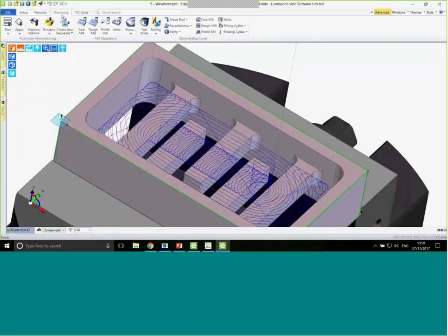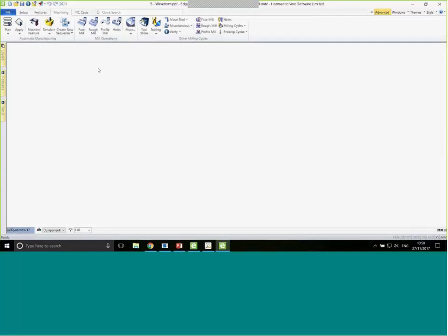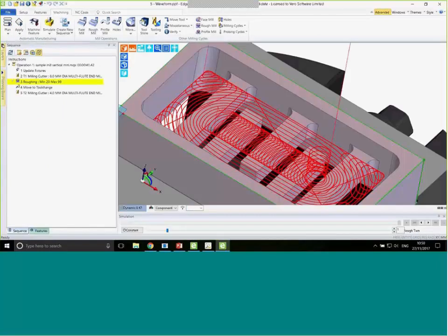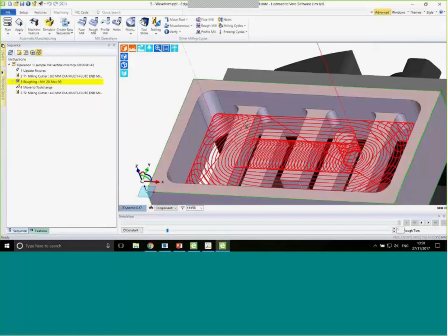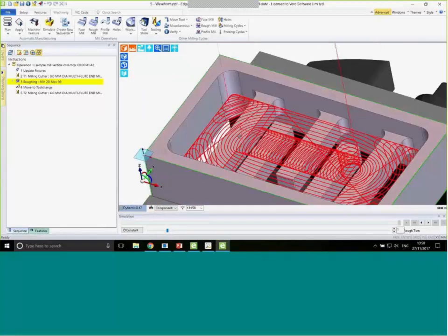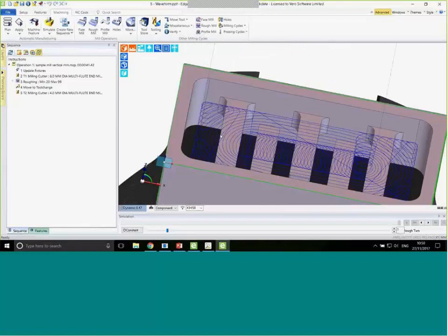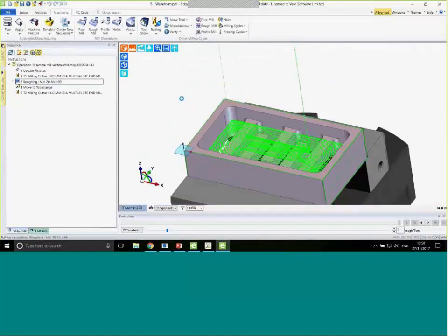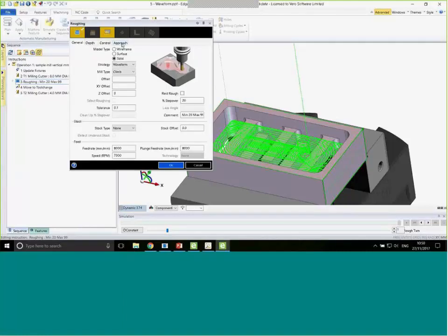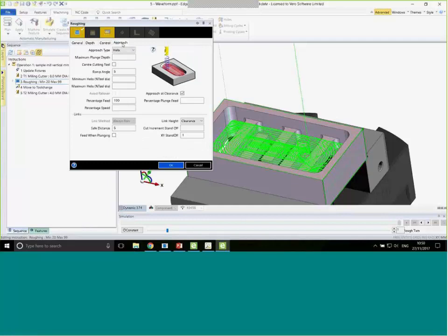So here we have a very typical toolpath, just on a little microwave part, lots of ribs and little islands, upstands, and we're finding that this toolpath won't go any deeper than the first level. It should really be going all the way down to the base. That's because of the radius of the helix that we've used in the past. The radius for the helix inside waveform approach has been set by Edgecam. You've not been able to dictate it, and what we see here on the screen is a pretty typical problem. They're not able to reach the base of the part.